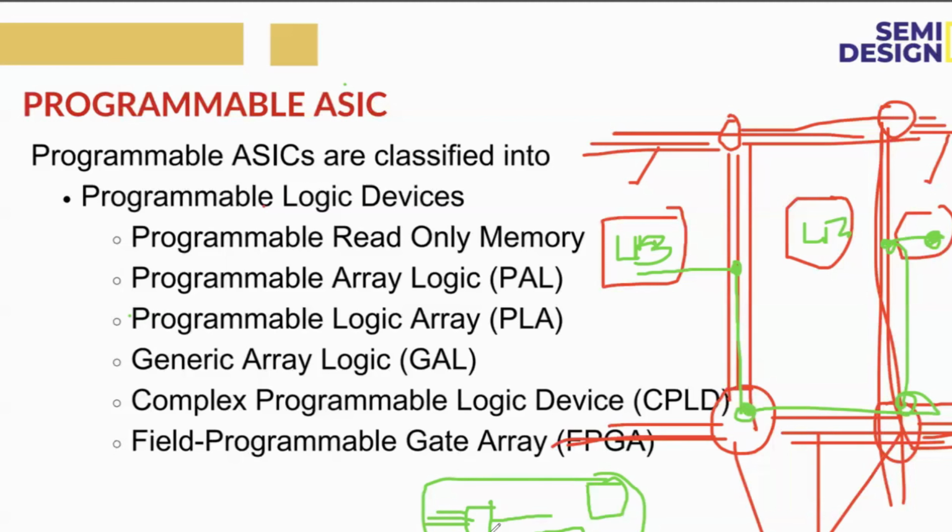That output we are giving to the flip-flop. So what is the flip-flop here? Mainly a register, not a flip-flop, a register. For registers, which flip-flop will we use? D flip-flop, right? The D flip-flop will store the data of the lookup table, and the output of the D flip-flop is given to the multiplexer. So the multiplexer will select the output. This is the simple block diagram we use in FPGA block diagrams. We classify in this way based on the different functionality and different blocks. Okay, everyone understood?